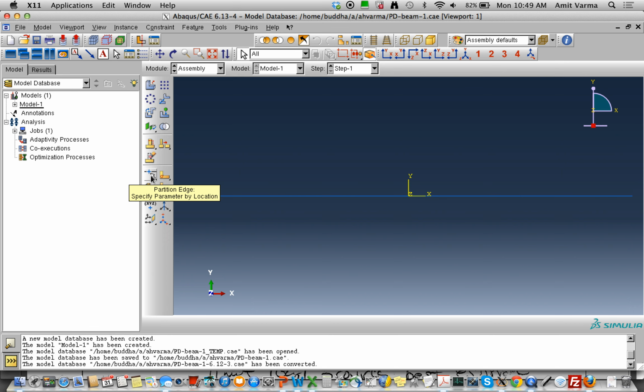Instead, it wants the load and displacements to be defined in the part, which means that in the part, you need to position a reference node right there, which you can do by cutting it. So you select the cut tool and provide a partition at 3/4 L, which will put a node right there. Do you see that? It's broken up into 2 lengths now. One is 25%, the other is 75%.